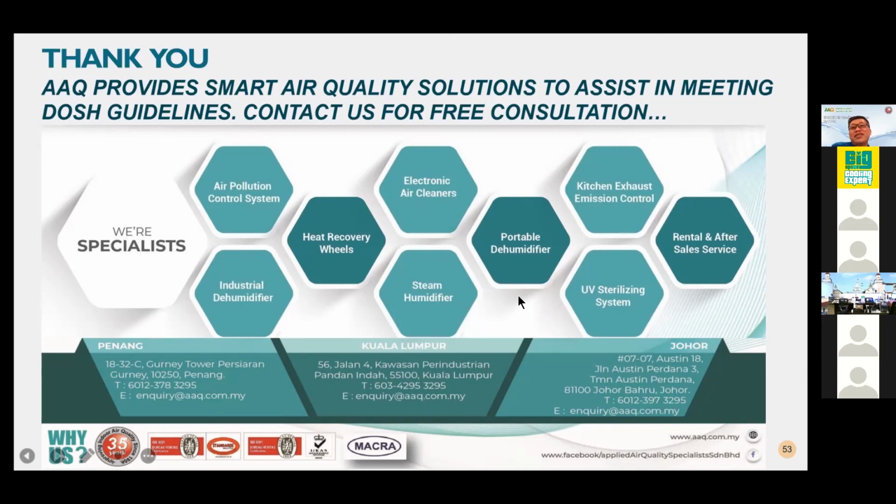So for GBI projects, everybody needs to recheck all the designs, because now we cannot use the recovery wheel anymore. I think this one is big. Something that all consultants need to check back in their designs. Maybe we can have an alternative of a bigger size pre-cool unit, or maybe we need to wait for testing of all the recovery wheel results. Maybe Eddy can respond back to DOSH.